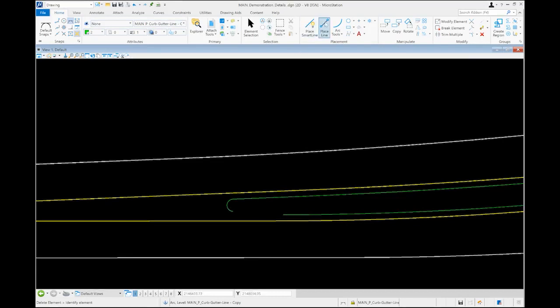In some cases, you can use just a standard tangent transition in between these, but just due to the proximity of this initial horizontal curve, we're going to end up needing to use an arc transition on this one. I typically use something in the 150 to 200 foot range, but there's some flexibility for this dimension. I'm using 200 foot for the purposes of this demonstration, just to give you an illustration.